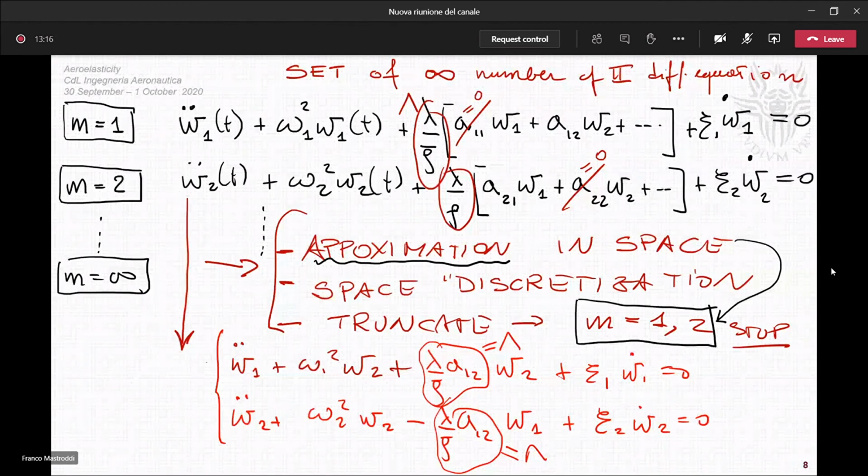In aeroelasticity, this implies that if you have a complicated aeroelastic phenomenon and you want to study this space-time phenomenon, you can space discretize your phenomenon and describe your fluid structure interaction in a limited bandwidth, selecting only a subset of your equations involving the poles in that bandwidth you are studying. Okay?